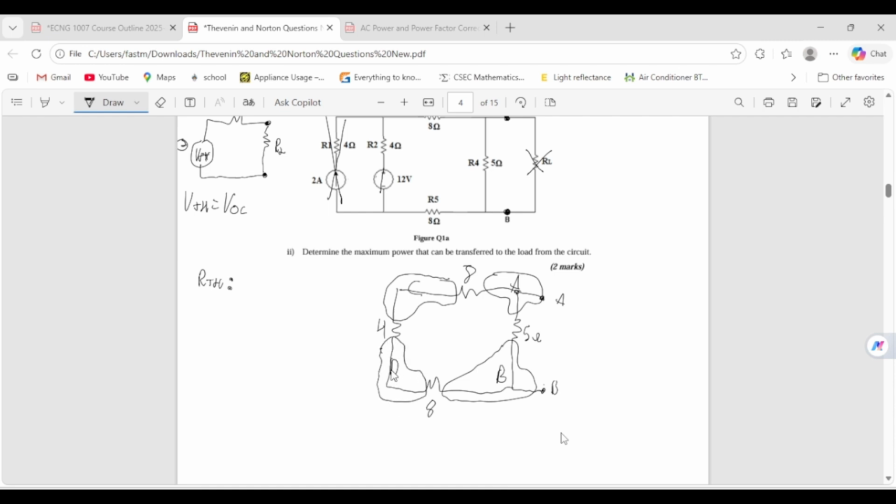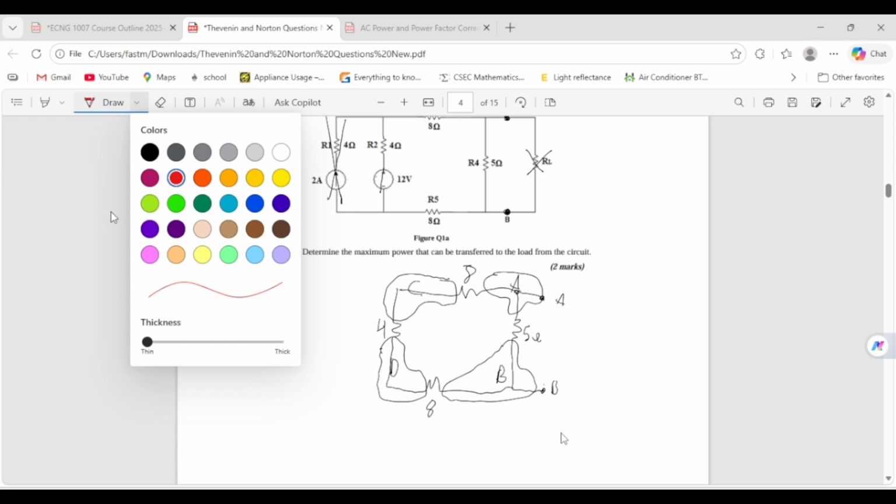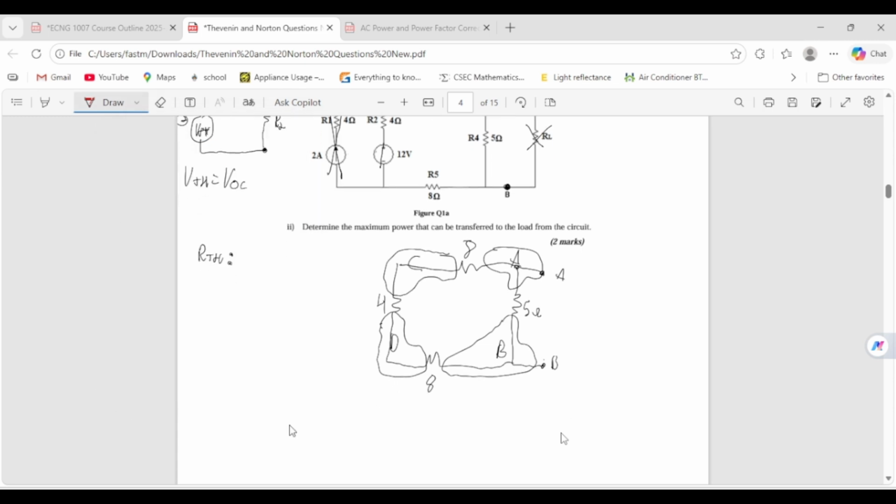So this one has 2 extra nodes in it, which will make a big difference. We start with A, and I write the nodes as a sequence, right? So A, then C, then D, and then B is the output. And that replaces resistors in between the nodes they're in. So this 8 ohm here between A and C, we'll write here. This 4 ohm between C and D, we'll write here.